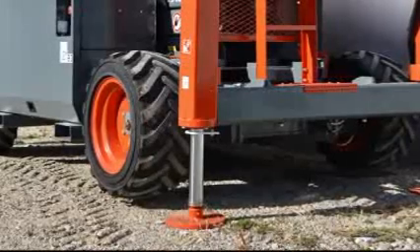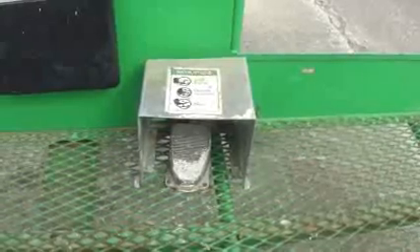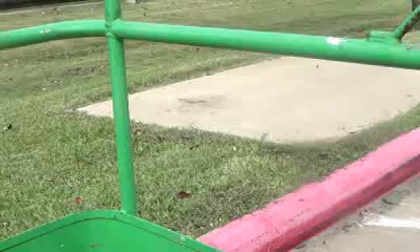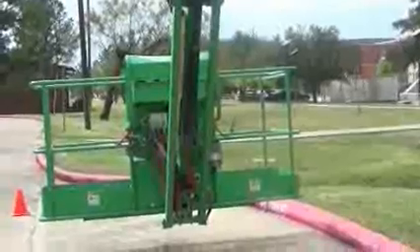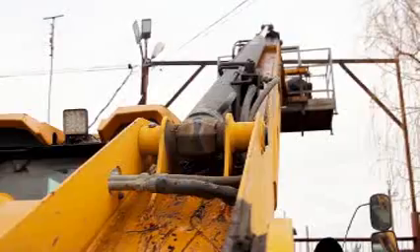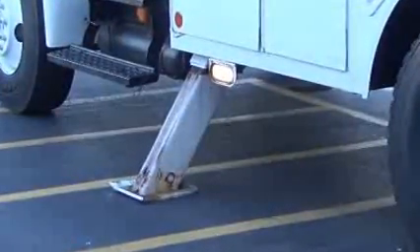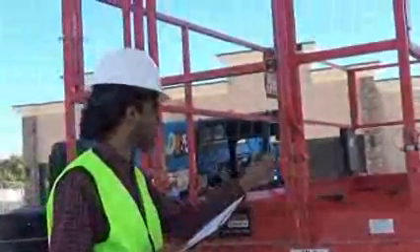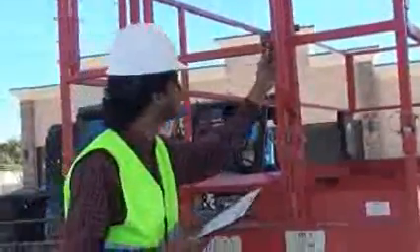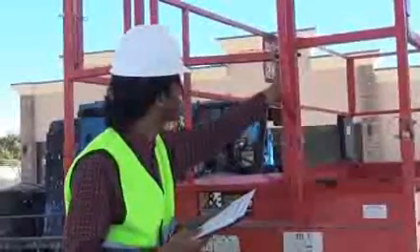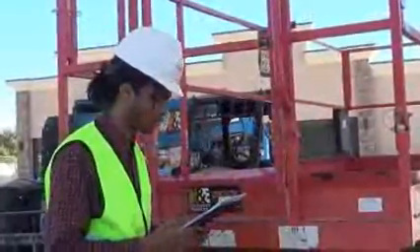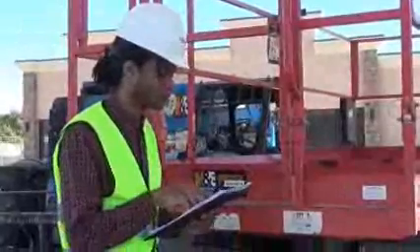structural items, stabilizers, and outriggers, work platform, guardrail system, floor, anchorage, and mounting, brakes, fluid levels, pins and pin securing devices, operation of stabilizers, outriggers, and other items as specified by the manufacturer. If you find anything wrong while doing an inspection, write it down on the inspection sheet, report it to your supervisor, and never operate an MEWP with problems.